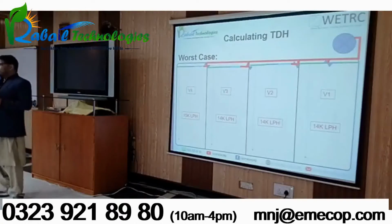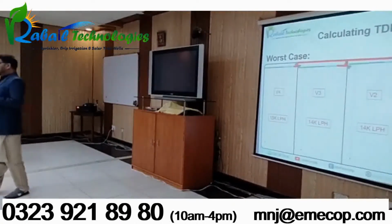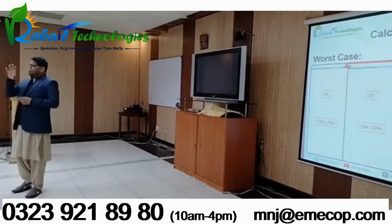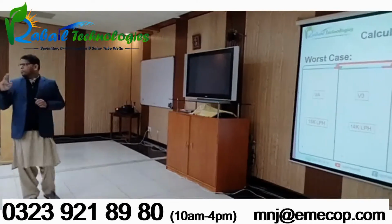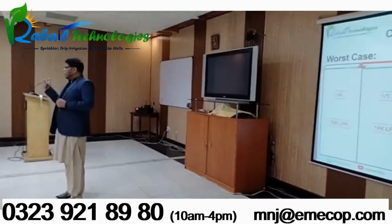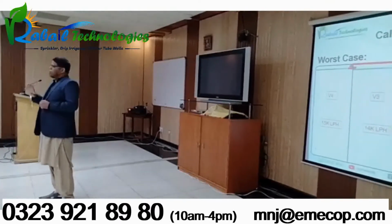Now the pipe designing is done. Now what we need to understand, or what we need to do, is how to design a pump. For pump designing, we need two major parameters. Number one is flow rate. Number two is total dynamic head, or the head against which the pump needs to operate.